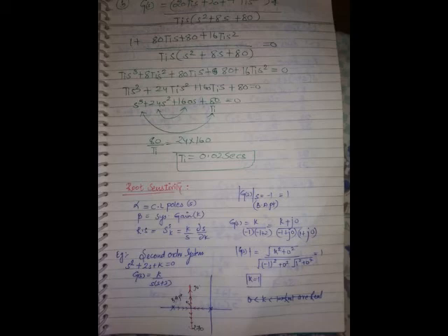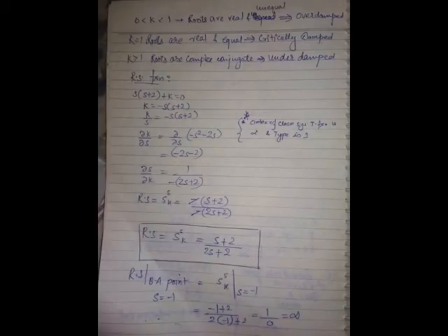These were all disadvantages. PD controller advantages: rise time reduces, bandwidth increases, stability also increases. Yes or no? And the advantage of PI is only that the offset error, the steady state error, is completely removed. These two advantages, of PD and of PI, are nothing but PID.